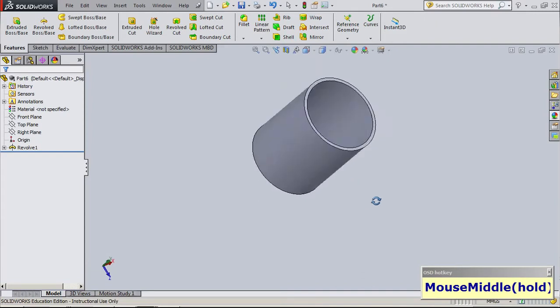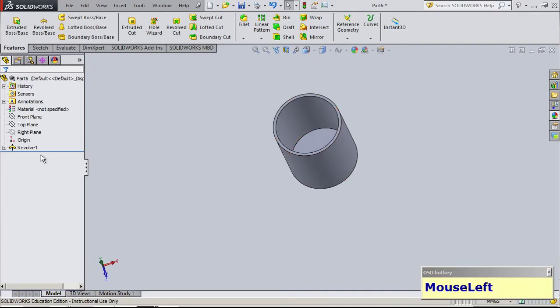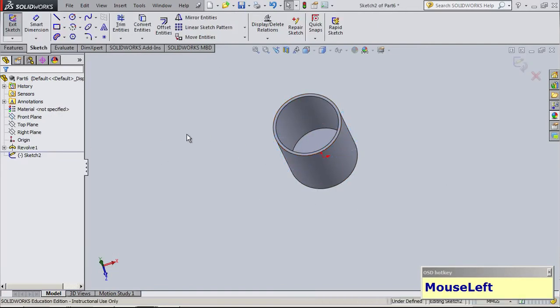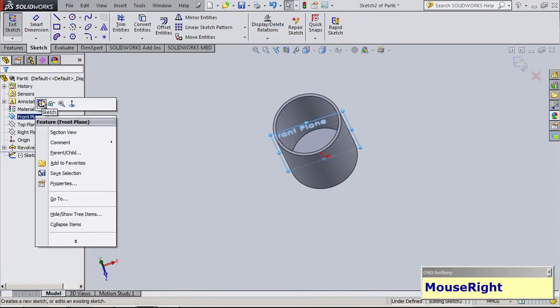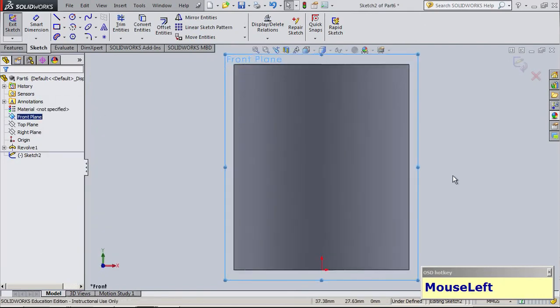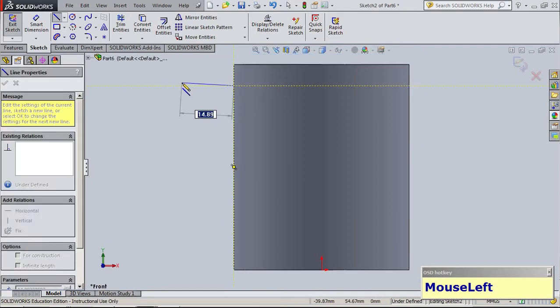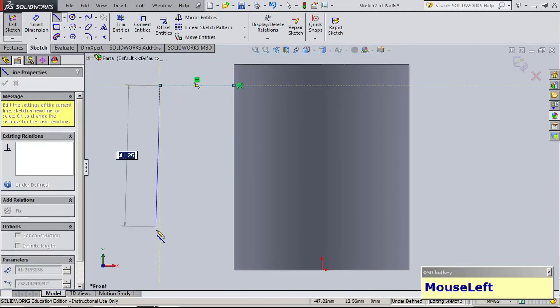This one doesn't look so nice, right? I can basically spend a little bit more time creating the handle. So if I wanted to create the handle, what I need to do is go back to the front view, normal to view, and then I'm going to create my handle on this side. So for the handle, we can make things a little bit interesting, but right now I'm just going to make it simple. So I'm going to have a rectangle handle like this.